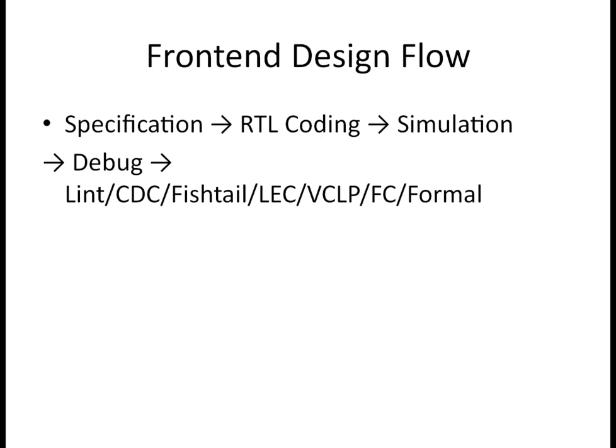synthesis, which will be done by Fusion Compiler. Even though there are many tools like Genus from Cadence through which we can do synthesis, in our company we'll be using Fusion Compiler, where we'll make sure your RTL is converted to a gate level netlist.